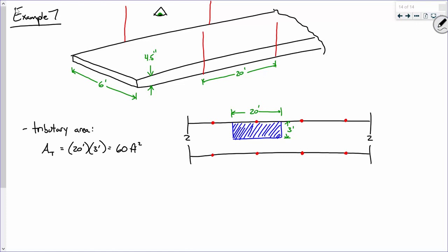Any questions? Now, let me ask you this. So we've got live load on this rod, right? I think that's the easiest one. How am I going to determine how much live load goes on a particular rod? What is the live load? Let's just start there. 100 what? PSF. So no, it's not pounds, it's pounds per square foot. It's a pressure, all right? So you tell me, how am I going to determine the force, the load on that rod?